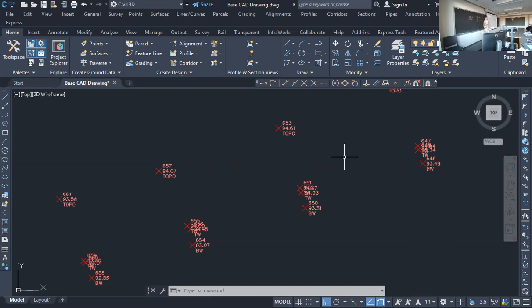4 foot. So your text in the drawing would be 4 feet high, so that when you printed it, it prints out 0.08 of an inch high when it's to scale. Everybody see that? I'm just taking how high I want it to be on the paper, multiplying it by the drawing scale, and that tells me what it is in the drawing.